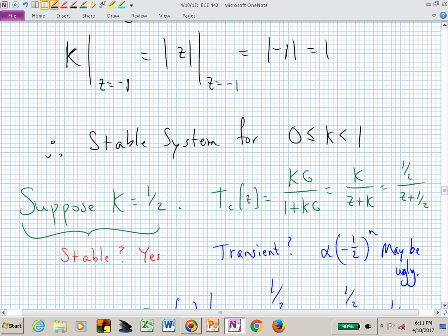the question was, if this is first order, I have a real pole. If I have a real pole, what do you know about percent overshoot, peak time, and settling time? Do all three of those exist? Do you have a percent overshoot for a real pole? No, this is just an exponential decay.